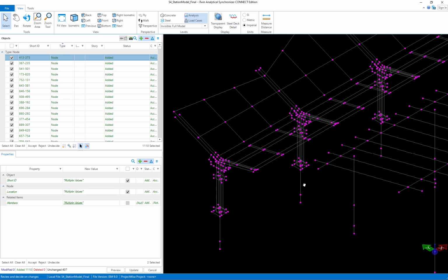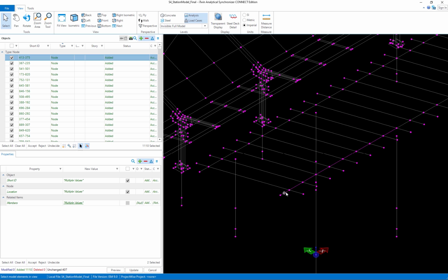What I am looking for, however, is to make sure that, say there's a girder member that's supporting a beam, those are drawn in the same plane, that their analytical lines are intersecting at a common node location. And this is where, if you are planning on starting a model with the BIM model, you will need to work with your architect very closely.